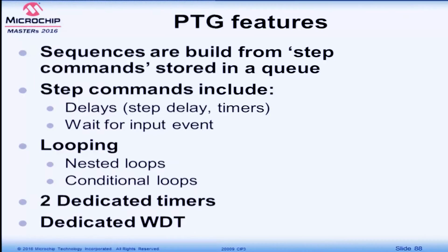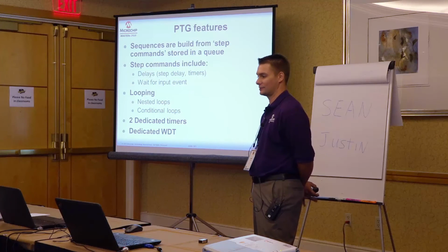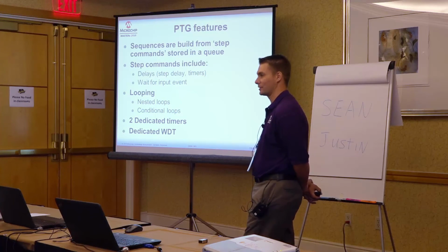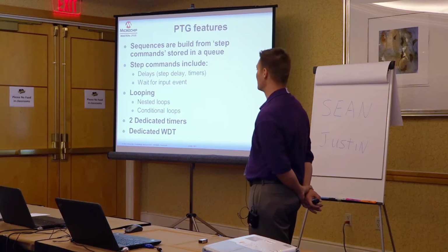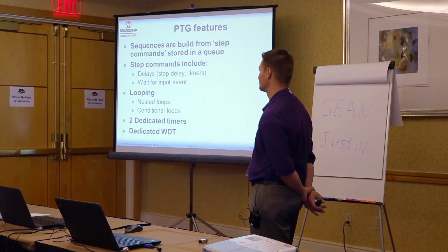Let's talk a little bit about the features of it. The sequencer is built from what we call step commands that are stored in a queue, so you would figure out what you want to do and put them in that queue and it'll execute them. Those commands include delays, either step delays or from timers, waits, waiting for inputs, so conditional things. It'll do looping, including nested loops and conditional loops.